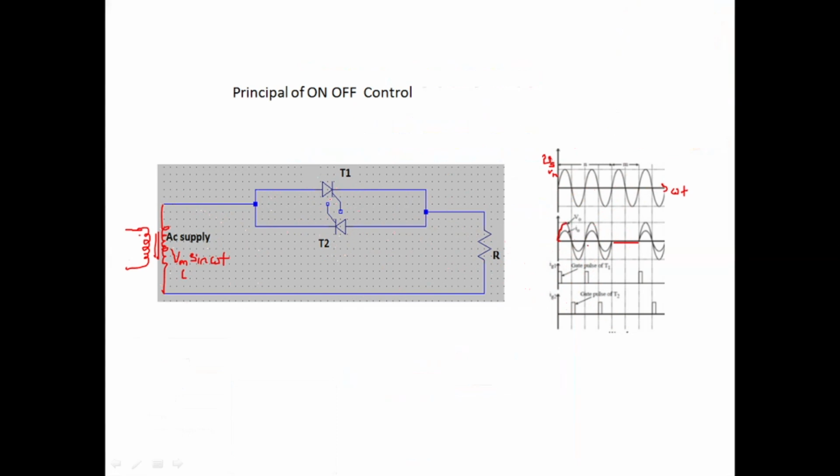Like this it continues. Okay. So this is the on-off based power AC voltage controller method. Here, for 2 cycles we have turned on the SCRs, and for 1 cycle we have not turned on the SCR. Okay, the same thing we are going to repeat.